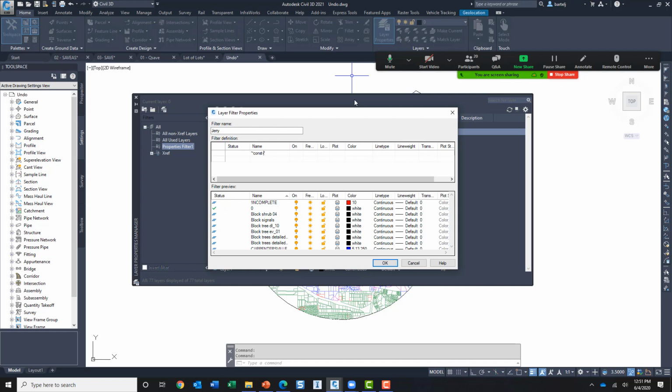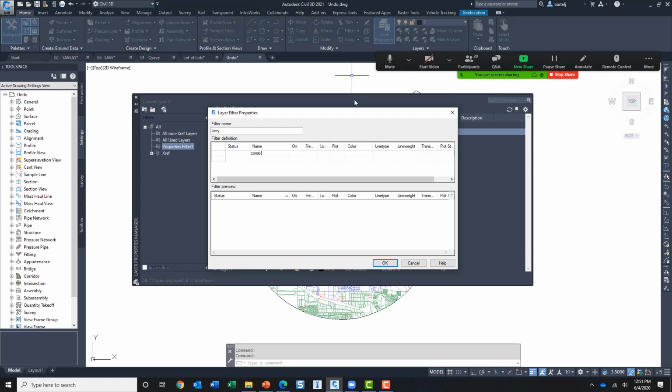That's going to show me all of the layers except for any of the construction layers. All right, so I can filter layers. I can use these for any number of things. I have one more that we'll do. We'll say construction. I can do some things in brackets. We'll say I want to do 1-3, and then I'll close brackets, and it will allow me to do that. I can separate things with commas.